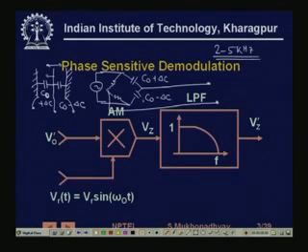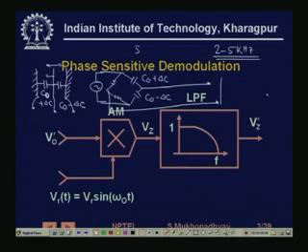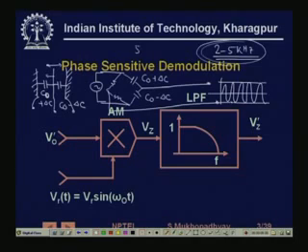On the other hand, any motion will be of the maximum, even if you take vibrations, of the order of tens of hertz or maybe 100 hertz. So, what is going to happen is that the output is actually a sinusoid of frequency 2 to 5 kilohertz, while the amplitude of this sinusoid is going to vary according to the motion.